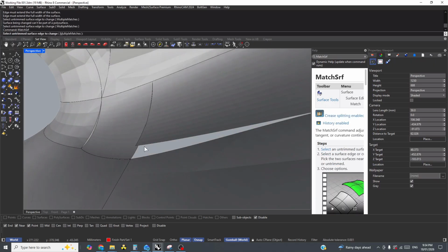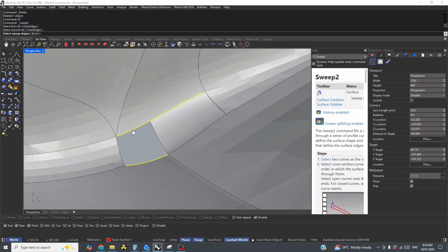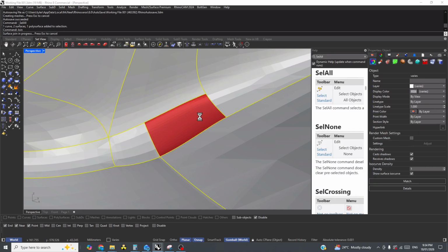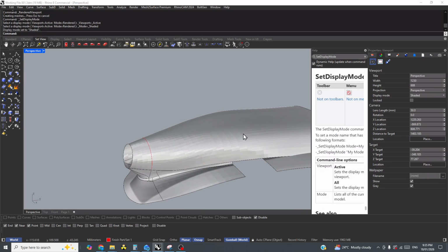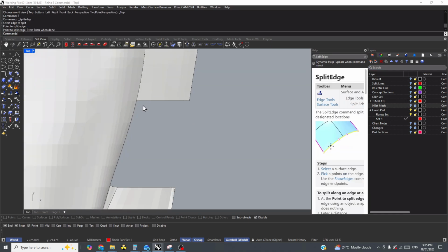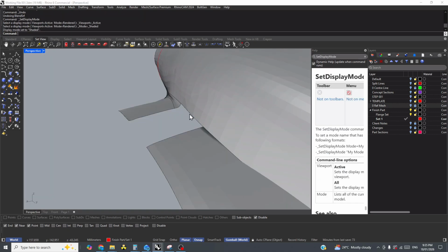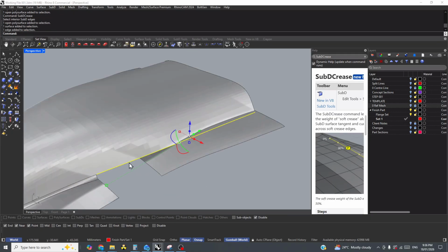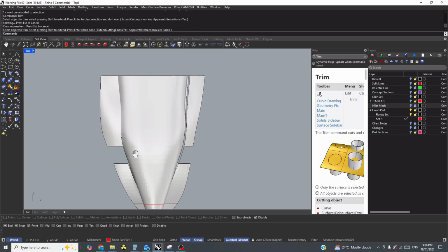It's often the case with reverse engineering that it's time, tolerance, and cost. You'll have different requirements from your clients, and in the world I work in, which is composites, it doesn't have a super tight tolerance. It's normally between, say, 0.3 of a millimeter to 1 millimeter, sometimes even plus minus 2, depending on what it is, acceptable.